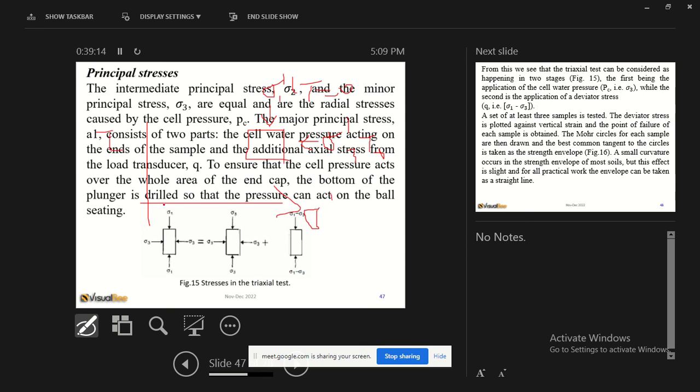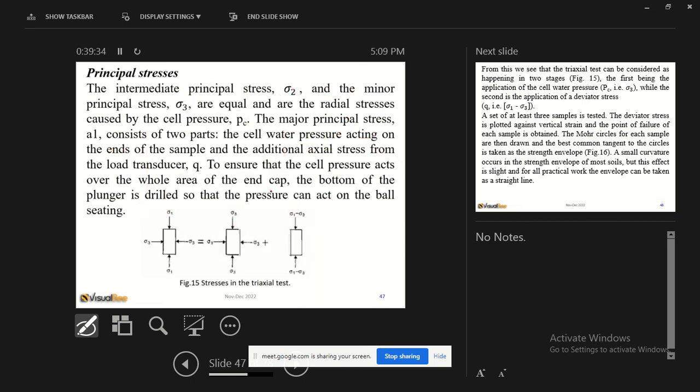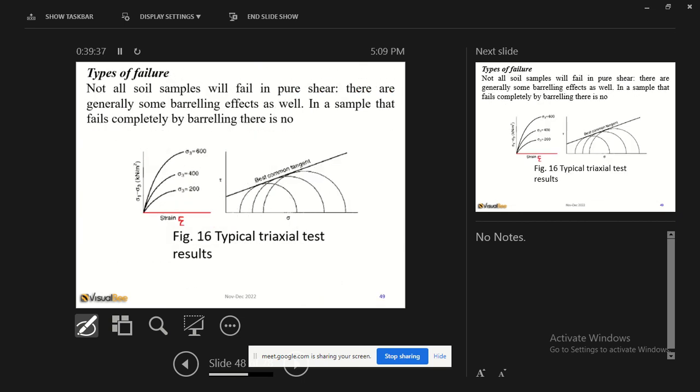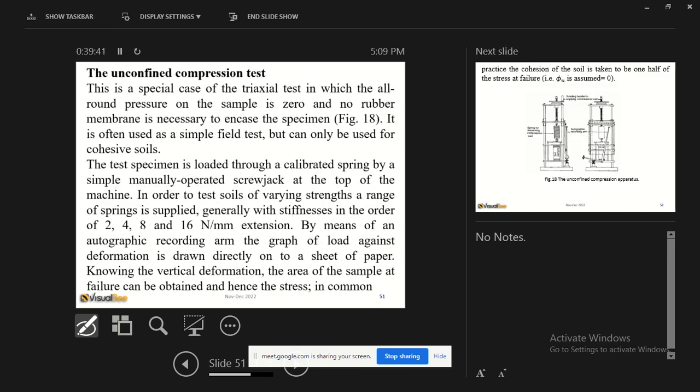So that this is sigma 3 and this is sigma 1. Please note this is so different from the triaxial test, because in the triaxial test you only measure tau and sigma, which is just one point on the tangent of the circle, which through trial and error you have to derive what the Mohr circle is. So that you read for yourself.